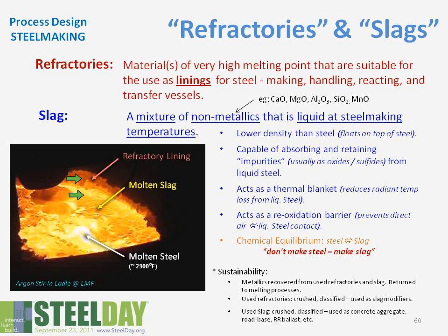Without that refractory lining, putting liquid steel into our ladle, which itself is made out of steel, would be analogous to putting a cup of hot coffee into a mug made out of ice. It's not going to be a good situation. So the refractory basically contains the liquid steel.